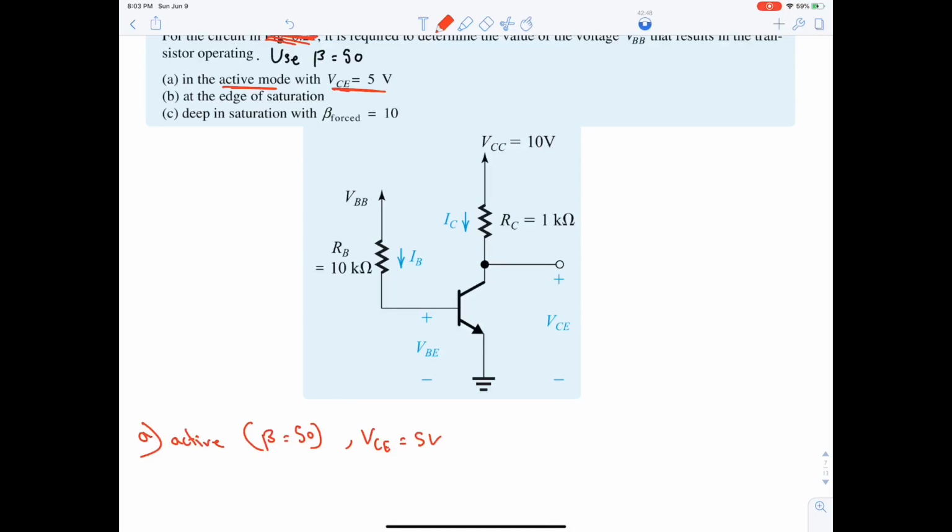Now let's start normally. What do we usually do? We find the type of the transistor. It's NPN. And then we have to label. The labels are already there, but let me write them again. VE, VB, and the I's are written except IE. Okay? Then we have to do the list.